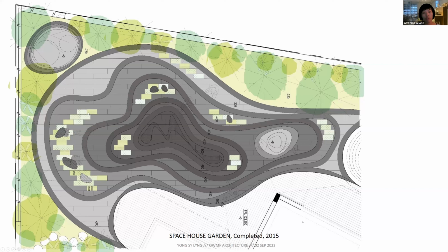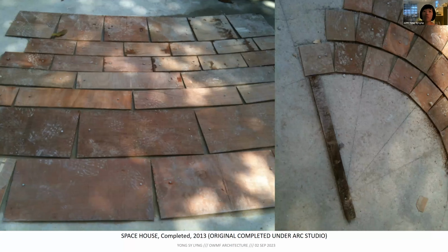These are cut on site by local craftsmen and installed on site, right? These are easy. They just trim off the edges. But this border is very difficult, right? It is precise, but there's also construction error on site, right? So we have to give more tolerance so that what they cut and deliver can fit on site, right? We learned from this mock-up that we did for the car porch